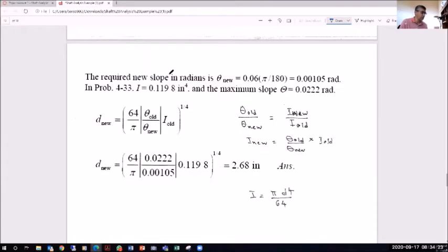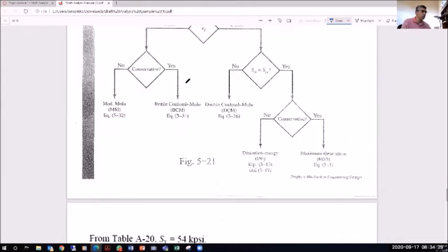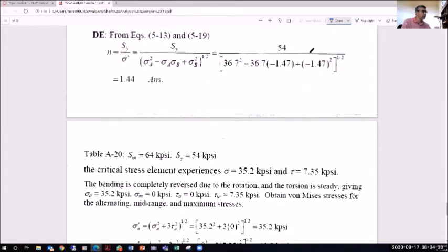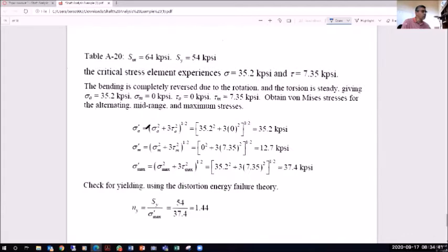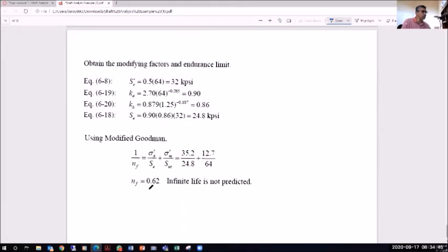I know I'm starting earlier, but I want you really to realize the difference between homework 3 and homework 1. With finding the stress, you can use the static failure theory to find a design factor N, and also use what you learned in fatigue to find the design factor for fatigue, NF.